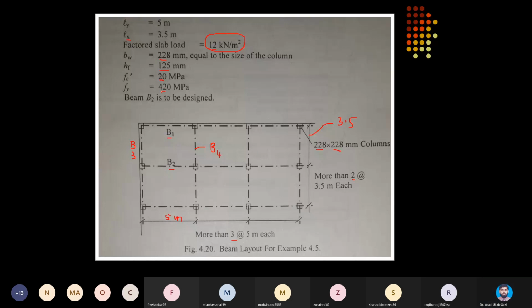There may be some restrictions from the architect that the maximum column size may be not more than this. It may be his recommendation, or the maximum recommendation may be that he or she wants circular or square geometry in columns. There may be a restriction that beam drop below the slab should not be more than this limit.